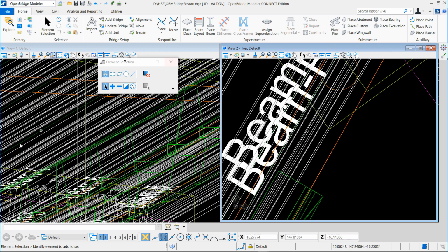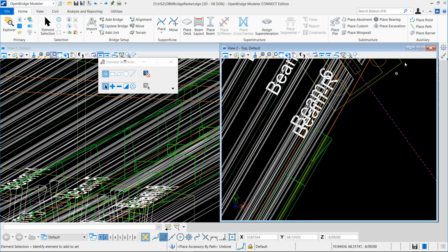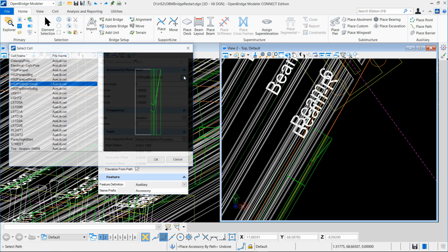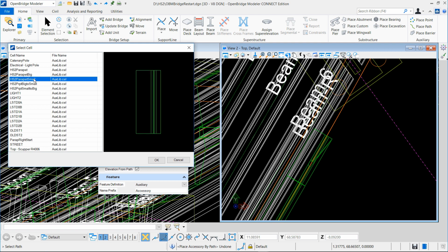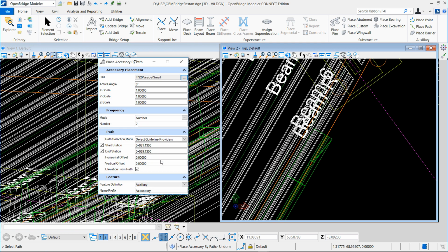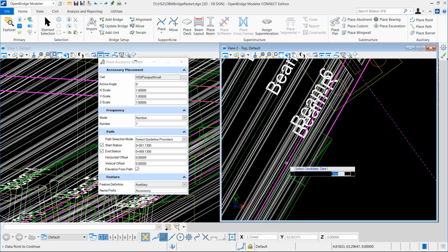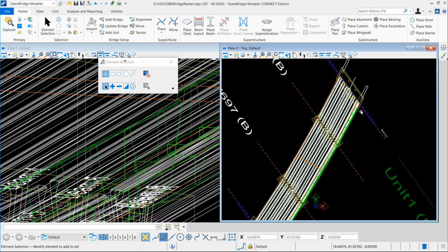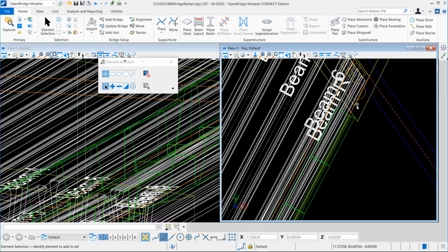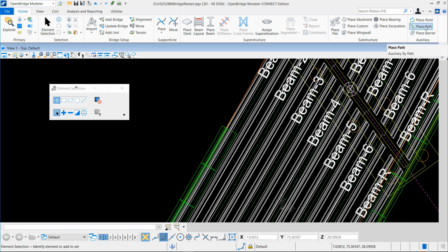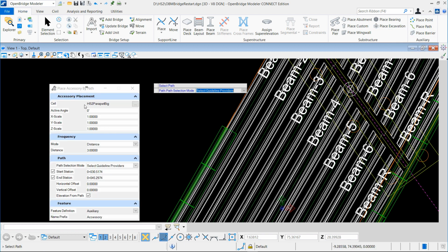So again, a parapet for transition, and finally the last one, with a specific one for the end because it's not the usual length. Here I just took the one from your model and placed it, but otherwise I should have placed a standard one, seen at which dimension I have to cut it with the skew effect, modified the last one by cutting it, put it back in the cell library, and placed it with OBM so it is recorded by OBM for the quantities.